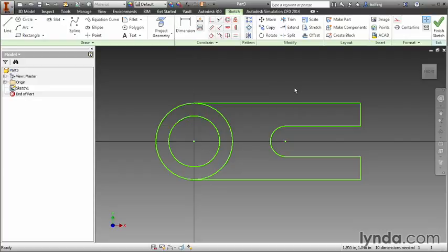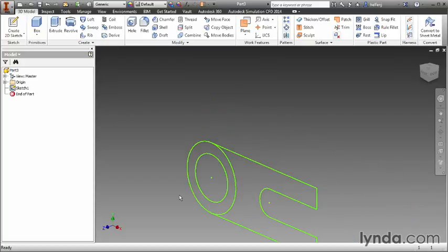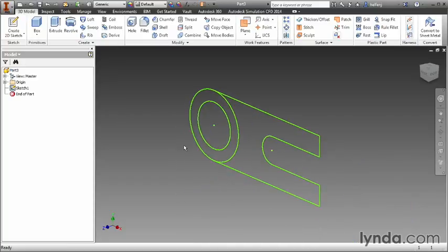Since we're not focused on that in this portion of the course, I'm going to go ahead and hit Finish Sketch, because I do want to call out another item when it comes to creating extrusions that'll come in quite handy for those who are importing from AutoCAD. And that's the ability to share a sketch. What you see here on the screen is the top view of my model. It shows the overall outline, it shows a slot that's sliced into it, it shows a hole that's available, and a boss that I'm going to add here. But they're all in a single sketch, and that's okay, and that's why I wanted to call this out.